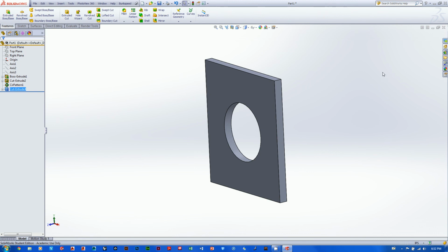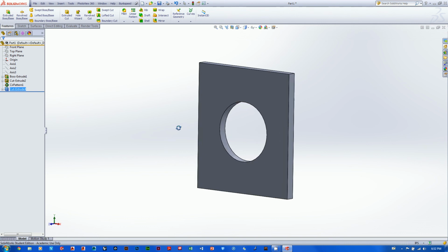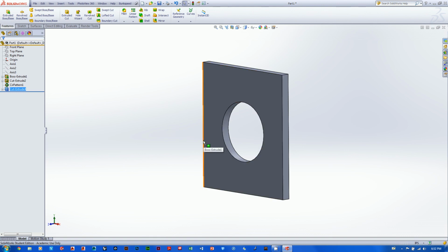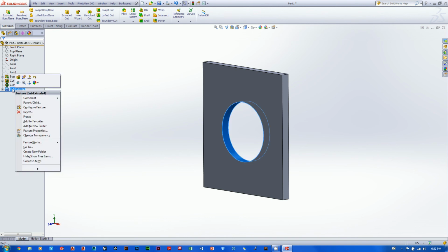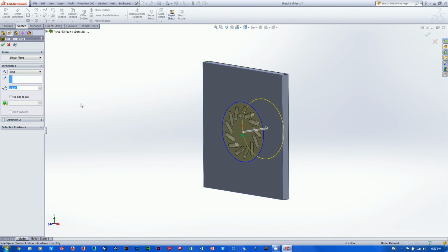Hey, so this is how SolidWorks works. You know, sometimes things go wrong, and you got to change them. So let's get back in there. Now, what I want to do, at Extruded Cut, cut everything that was inside of its extrusion. I'm going to go ahead and edit that feature now. I'm going to go here to Edit Feature, okay? And I'm going to look here.